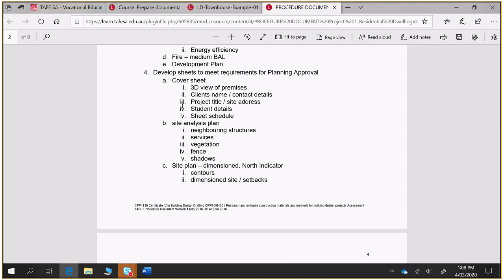And that cover sheet is where you can basically say, draft slab construction, load-bearing construction as per AS 1684.2. Yes, exactly. So all timber framing as per AS 1684/2010, residential slabs and footings as per AS 2870, etc. And steel framing, or timber framing?